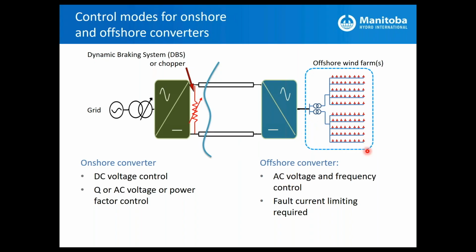As a result, when the wind turbines operate in active power control mode, this bus emulates the effect of a slack bus. You basically push the power because the turbines are synchronized to the voltage produced by the offshore converter.